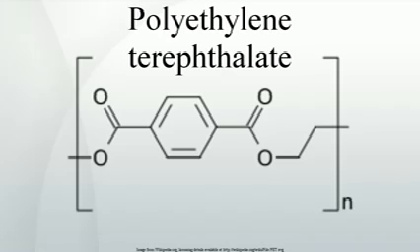manufactured on the line. This aim is solved by degrading the PET bottle flakes, already during their first plasticization, which can be carried out in a single or multi-screw extruder, to an intrinsic viscosity of about 0.30 dg by adding small quantities of ethylene glycol and by subjecting the low viscosity melt stream to an efficient filtration directly after plasticization. Furthermore, temperature is brought to the lowest possible limit.